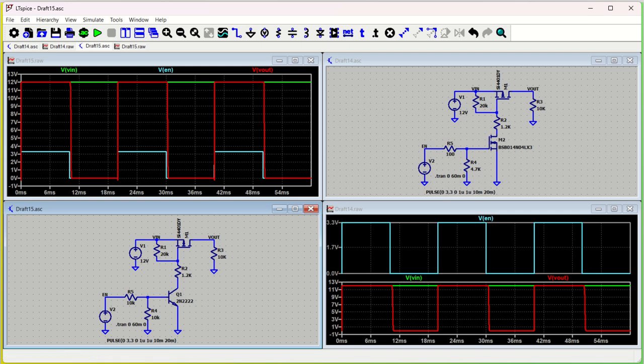So hope you now have a very good idea about how to design this particular circuit and understand how we can drive our load from the system supply or from sources such as a battery or maybe a regulated power supply. But you have to make sure the MOSFET that you are choosing, that is the P-MOSFET, has a high enough current carrying capacity so that it doesn't fail. Like source to drain current must be good enough. Let's say you have a requirement of 1 ampere, then you choose a MOSFET rated for a minimum of 3 or 4 ampere, then it will be a very good design.